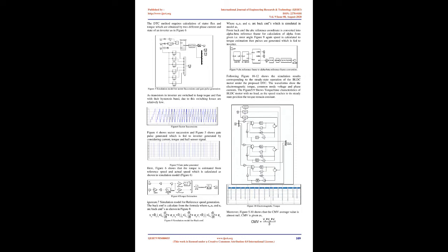3. Simulation and simulation results. A simulation of direct torque control of BLDC motor drive. The simulation model for DTC of BLDC motor drive is shown in figure. The overall system consists of two loops for torque and stator flux. The stator flux and torque reference values are compared with actual values taken from the motor stationary reference frame model, and from this errors are calculated for analysis.